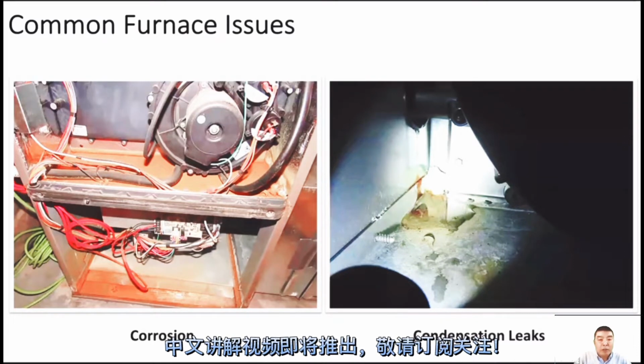But sometimes, you should know, the category 1 you can find like this too, maybe at the bottom here. If a category 1 furnace is rusted like this, normally that means there's an air conditioner A coil just above the furnace.